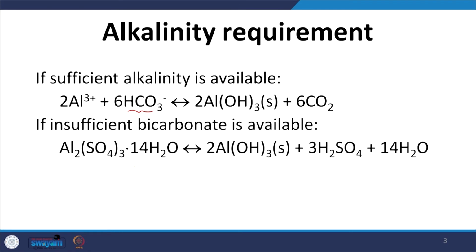If not, you will have this being formed, but H2SO4 will not stay as H2SO4. It will immediately dissociate into 2H plus and SO4 2 minus, let's say, right? H2SO4 will dissociate. Why? It's a very strong acid, pKa is pretty low. It might not go to 2H plus directly, it will go to H plus and HSO4 minus, and then H plus and SO4 2 minus. Again, H plus will be released and then the pH is going to decrease. So that's why alkalinity is required, let's say, right?